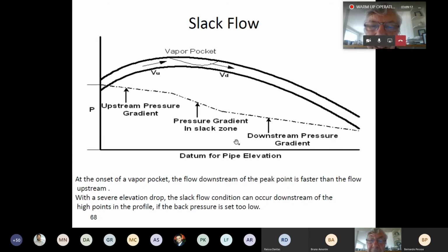You've also got to be careful of this when you're doing hydrostatic testing, by the way, because if you get your water source from a river and there's a lot of air in it, then the air can form a pocket like that. You actually have to drill into the pipe locally to draw off the air. You'd never get the pipe emptied of water.